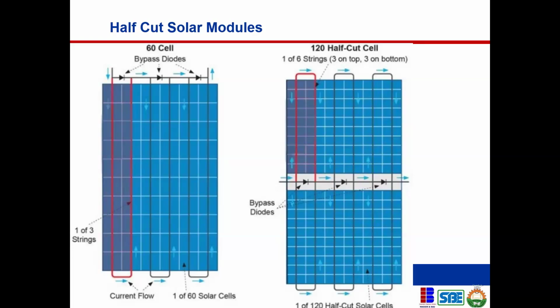Okay. Now coming to the second question on the number of cells, right? Sometimes there are some basic tests that we also do to verify the ratings of these PV modules, using a basic multimeter, looking at the voltage, putting it in the sun, and seeing what this PV module gives.